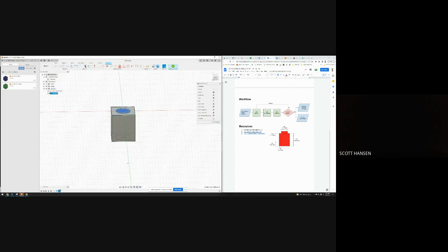So clicking that circle, let me finish sketch. Clicking that circle, hitting extrude, and let's make this little circle on the top 1.6 millimeters as well. Make sure your operation says join so that it'll keep this all one block. And you should see in your bodies, we want to keep this one block.